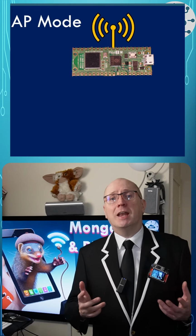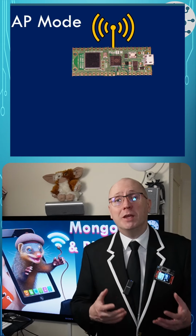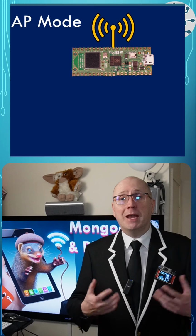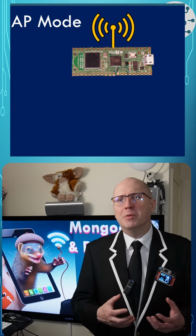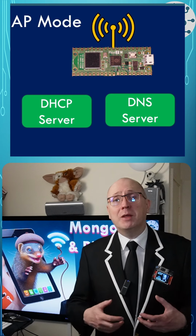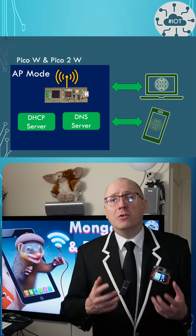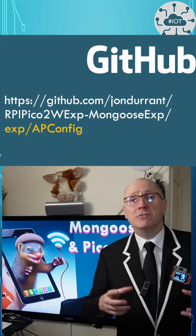The first challenge for this project is to be able to put the Pico 2W into an AP mode, i.e. offer a Wi-Fi service for my laptop to connect to. That's a little different from station mode in that I need to provide a DHCP and DNS service. Fortunately, the Raspberry Pi examples have already produced such an example with those two services, and I can reuse them in my own example on my own GitHub repo.